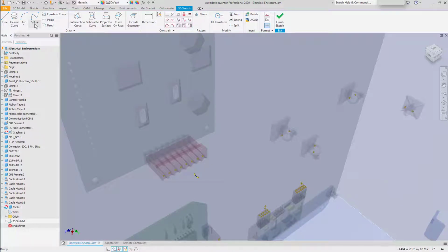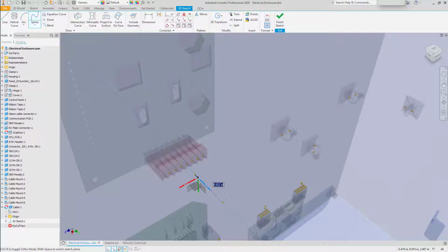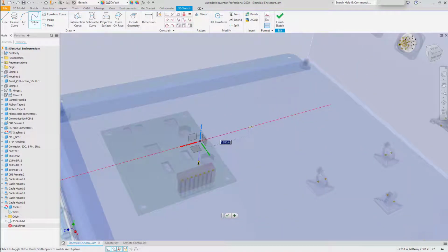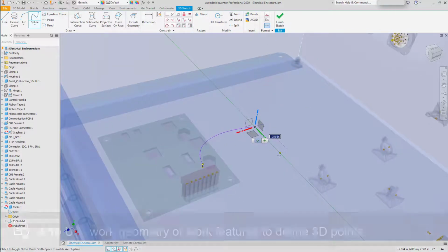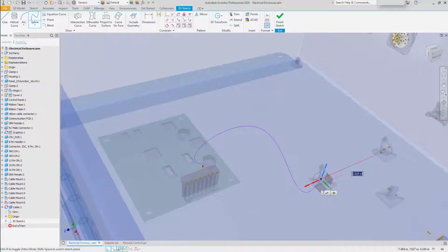In this case, I'll use an interpolation spline, which will allow us to follow points more closely. I'll select the endpoint of a line. Then, using the right-click menu, make sure to switch on ortho mode to begin. This will allow me to go along a direction, then transform down X, back down Y, and then begin picking points directly in the model.